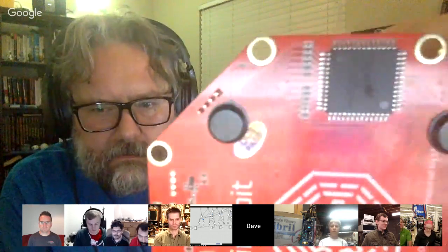One of the neat things is you have all these LEDs, but because there are so many LEDs, it's using the Holtek HT1632 that you guys use for some of your LED matrix controllers. That offloads all of the processing for controlling and multiplexing the LED array from the MCU. So it lets the MCU run at full speed without taking cycles for the LEDs, which is pretty impressive.